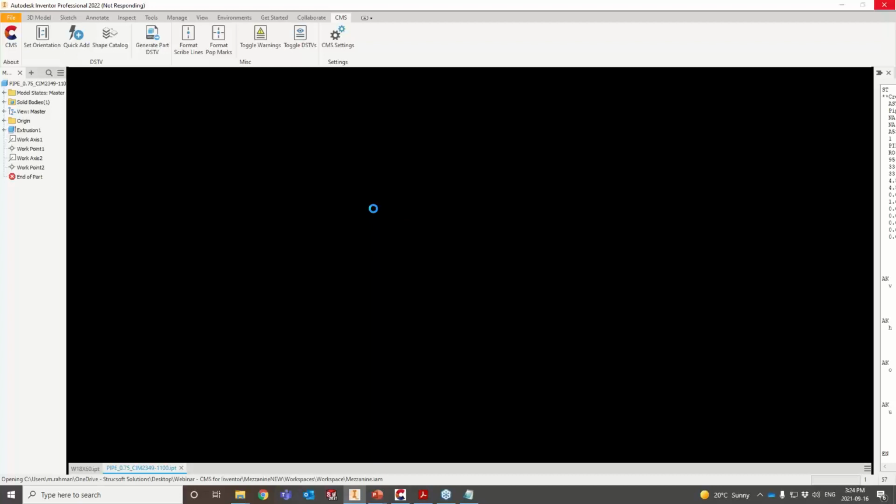You have to open your sub-assembly, and as long as on that sub-assembly level you have access to your part level. What I'm trying to say is, you have access to your raw content, and from there you can just create the NC1 file. So you have to open your sub-assemblies manually and run your DSTV command from there.